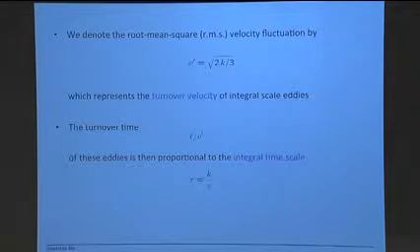So that's a very important one. The velocity scale, the fluctuation scale, can be defined from the turbulent kinetic energy. That's basically just the square root of the turbulent kinetic energy. So that's kind of a turnover velocity, and with these two, a length scale and a velocity scale, you can define the time scale also just by L divided by v prime.